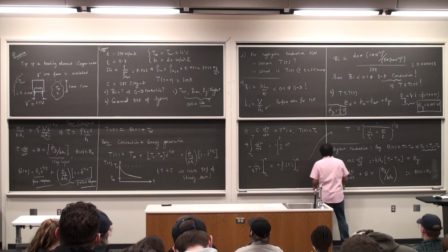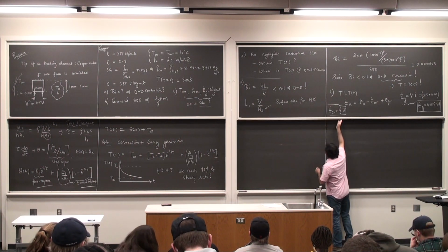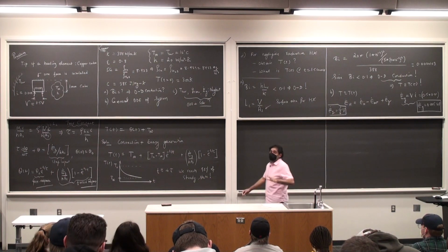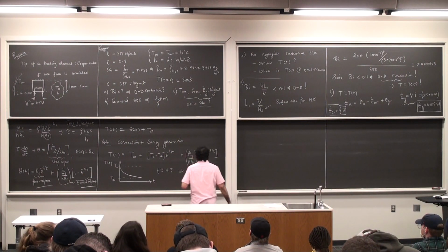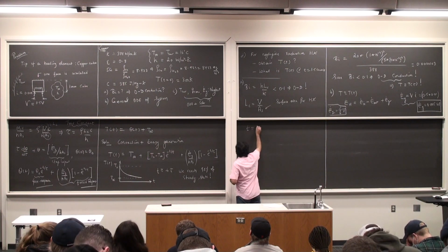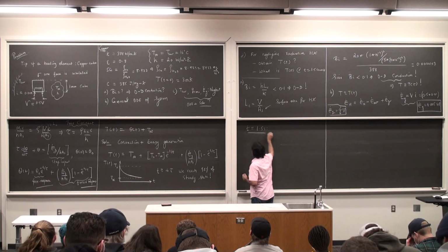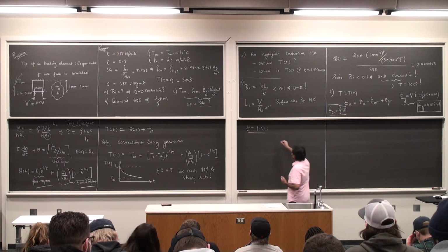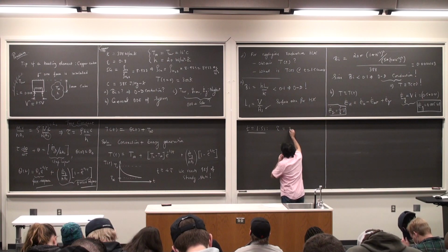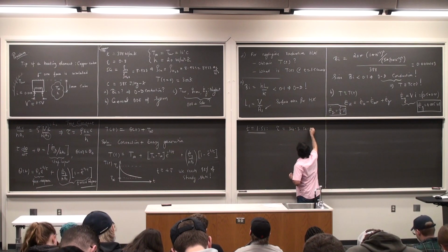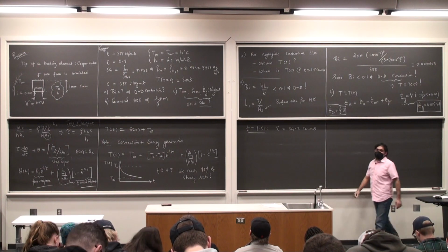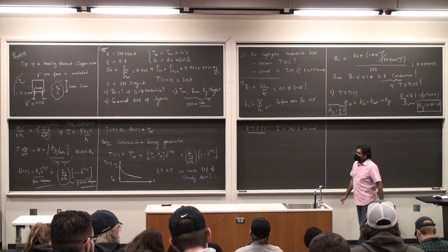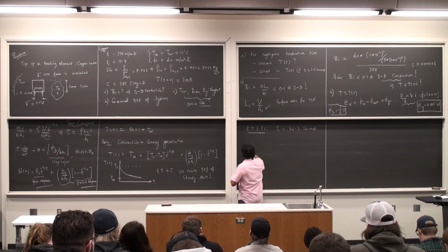Very last bit of the problem, just some plug and chug. Your homework is nothing more than this, okay? For the conduction, zero-dimensional transient conduction, at least it's all mostly this. So at t of 1.5 seconds, I need to calculate my thermal time constant. If you plug in the values, this is approximately 34.3 seconds after you do the plugging in of all the values using the expression for tau, and with all the initial conditions and so on,